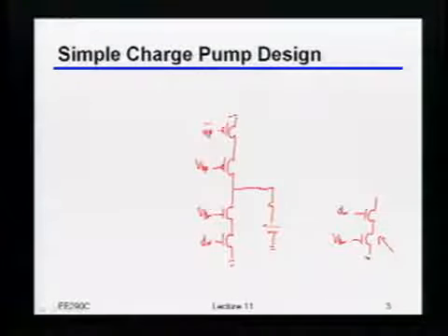And by the way, you should start thinking about second order effects, because remember, this is a pretty sensitive thing that you're going to want to have be very, very clean, because this is really going to come into the jitter performance of your overall loop. Any thoughts? Because of the digital, any noise on the digital line will not get directly coupled onto the integration capacitor. Okay, actually that's not a bad reason.